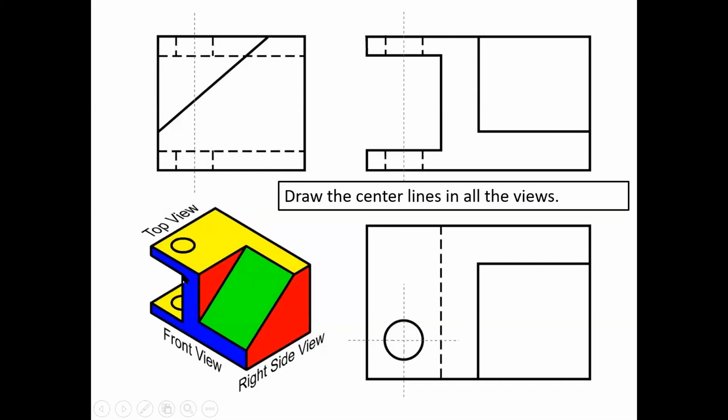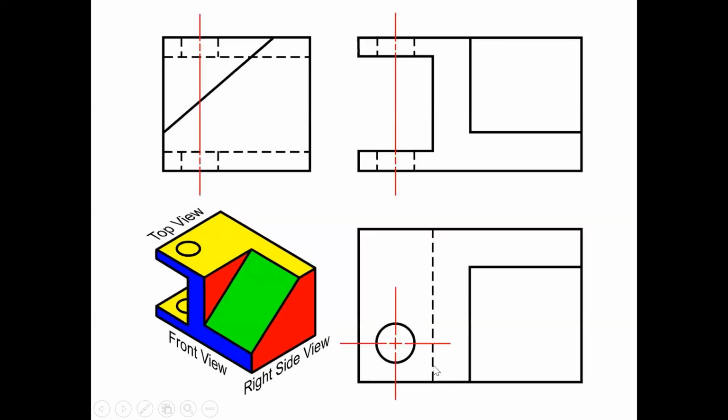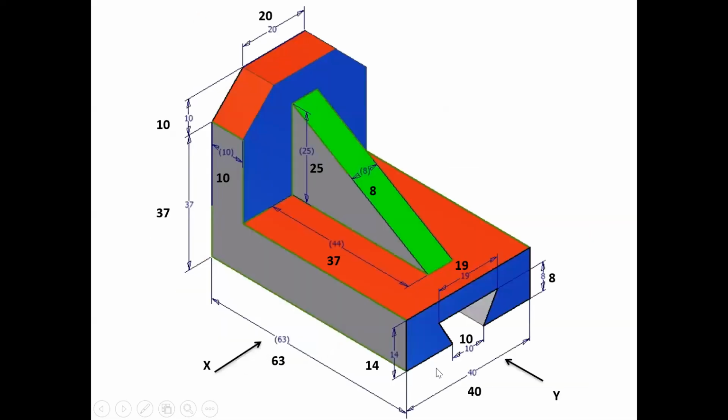And when you see from the top, this corner is not visible, so I am going to take the projection from this line and you have to show it by hidden line. Getting? So you can see here one of the examples of how it is required to draw.